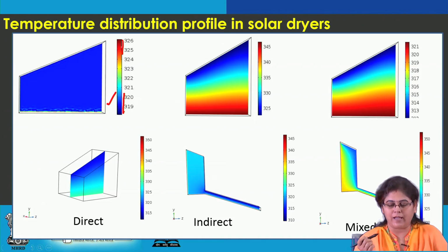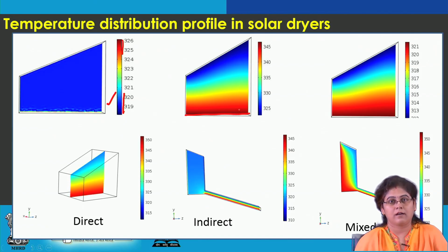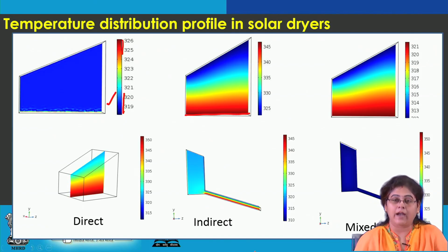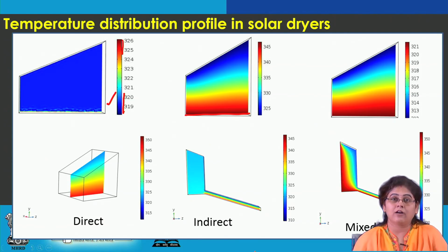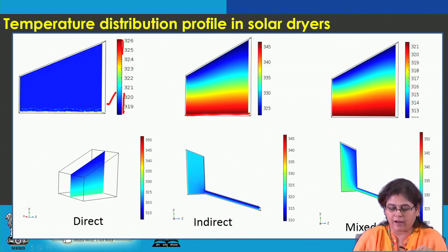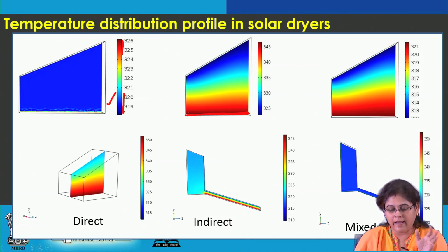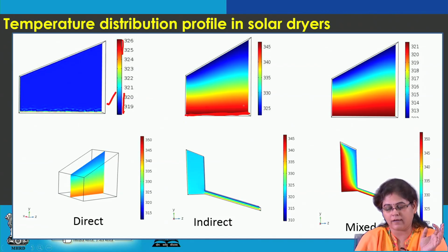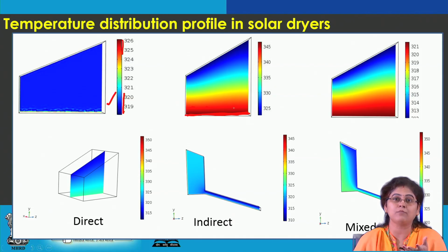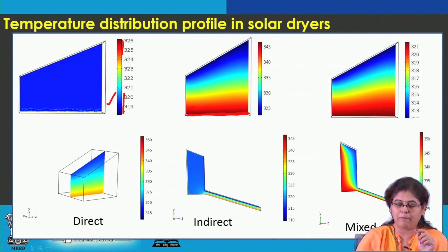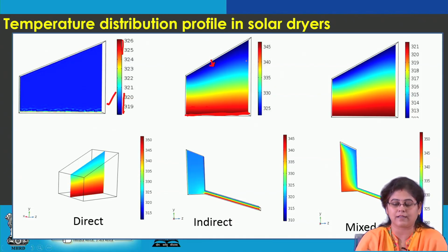With progress of time it was observed that the beneath part is the absorber plate, which is already painted black, and in the experimental period this black absorber plate is getting heated up quickly due to the absorption of solar radiation. The air layer just adjacent to the absorber plate is red in color, that means it attains the maximum temperature, and at the same time the temperature beneath the glass cover is very low, as represented by the cold zone in blue.